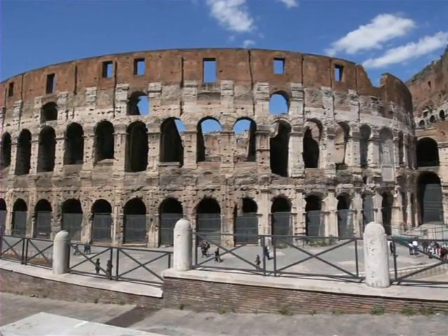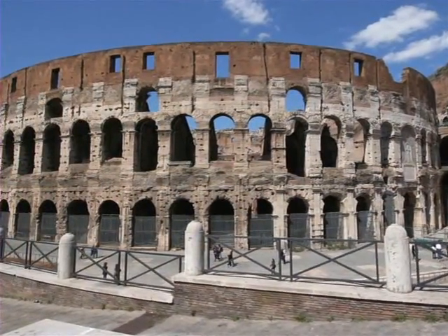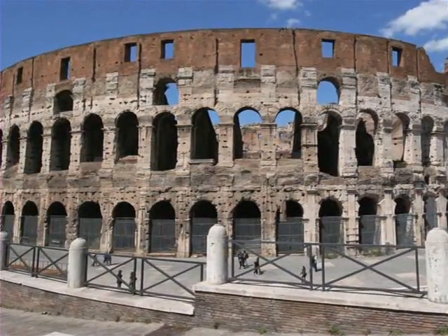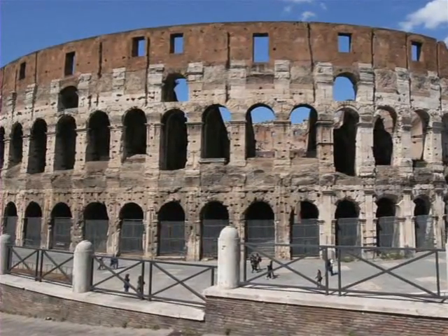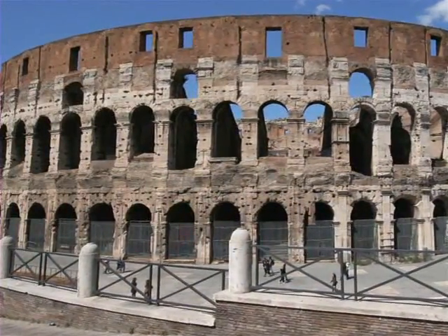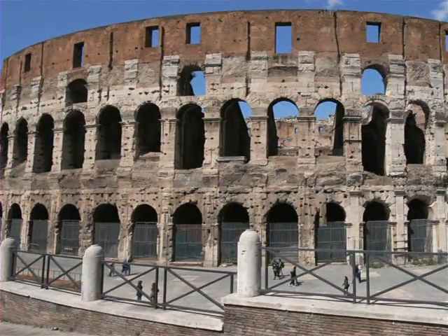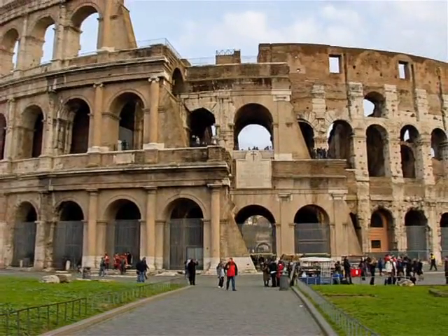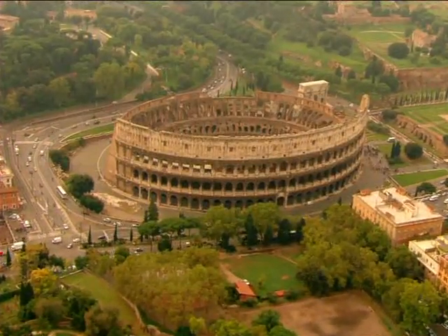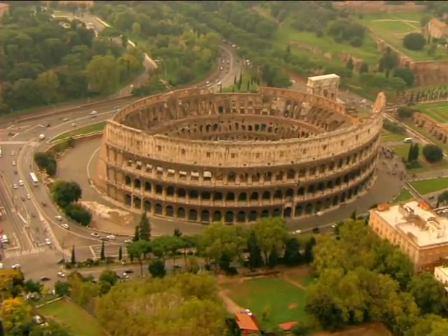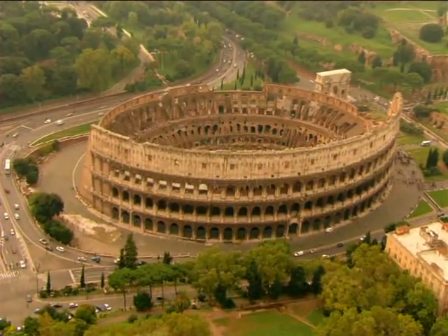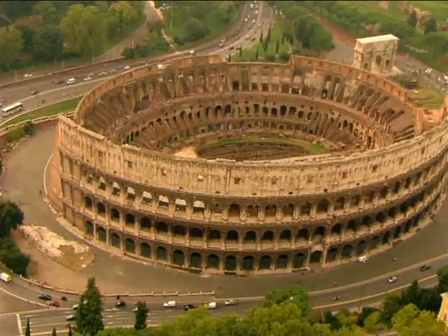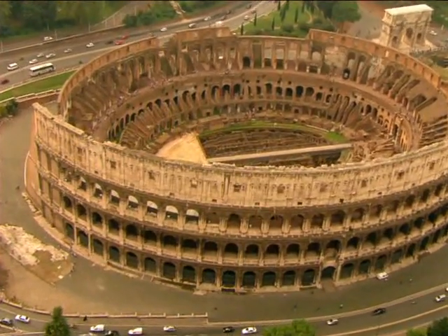From an engineering perspective, the fundamental structure of this building is a series of 80 barrel vaults arranged radially around the first level. These form the main entrances to the amphitheater and also the foundations on which those upper arcades and the concrete seating area were supported. Like the arcades of the Pont du Gard, the barrel vaults of the Colosseum support each other laterally. But unlike the Pont du Gard, the vaults require no additional external lateral support because they're arranged around the perimeter of an ellipse. Every arch is laterally supported by the arch on either side of it. There are no ends in the arcade.